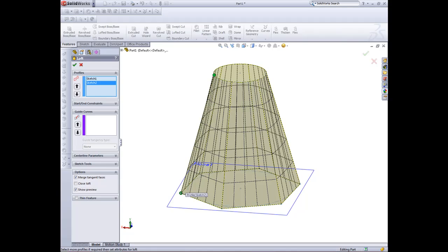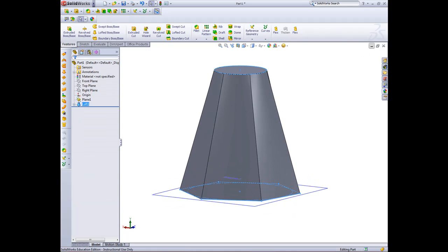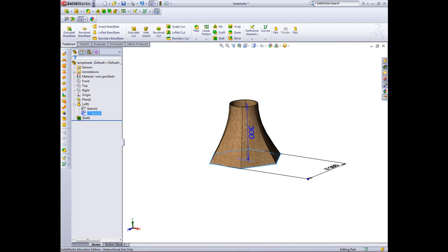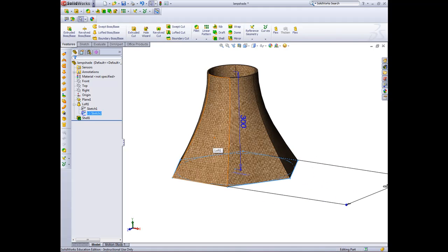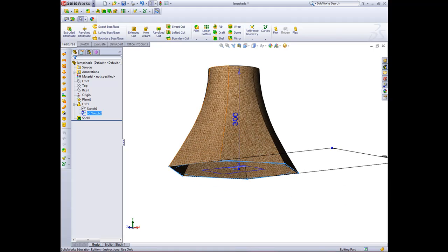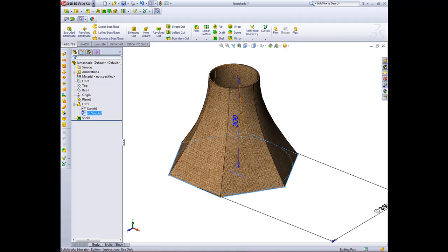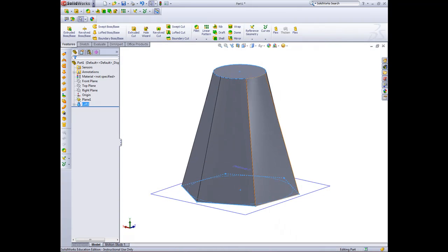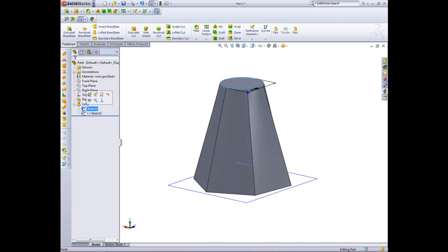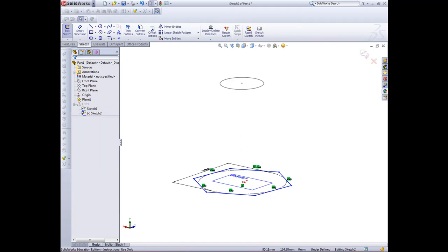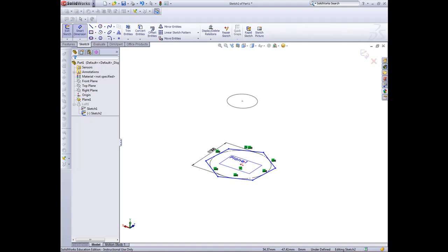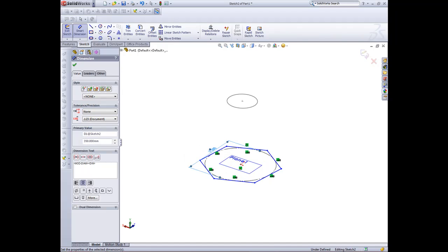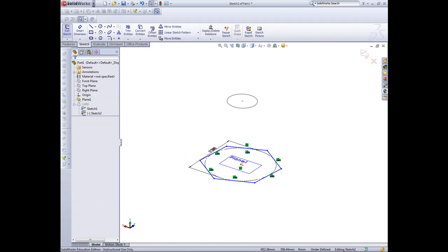But you can notice at the moment, if we go back into our other lampshade that I created earlier, one, we've actually got to change the dimension, but it actually goes also curved down into there. So there's another tool we can use to do that. First of all, though, we can just go back into our sketches. Right, so this sketch here, we need to change dimension to 350. Okay, green tick that, and I can exit out that.